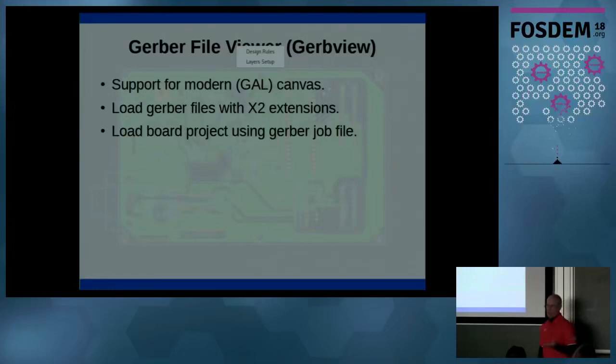They will load with the Gerber X2 extensions, and there's currently work underway by the Gerber folks to come up with a new file called a job file format, which is basically a definition of your entire board: the stack up, all the different layers, how they're stacked up, the widths, and the distances between each layer. There's what's called a project or job file, which you can send to your board house, assuming they support that, so you don't have to tell them the layer stack up and everything.